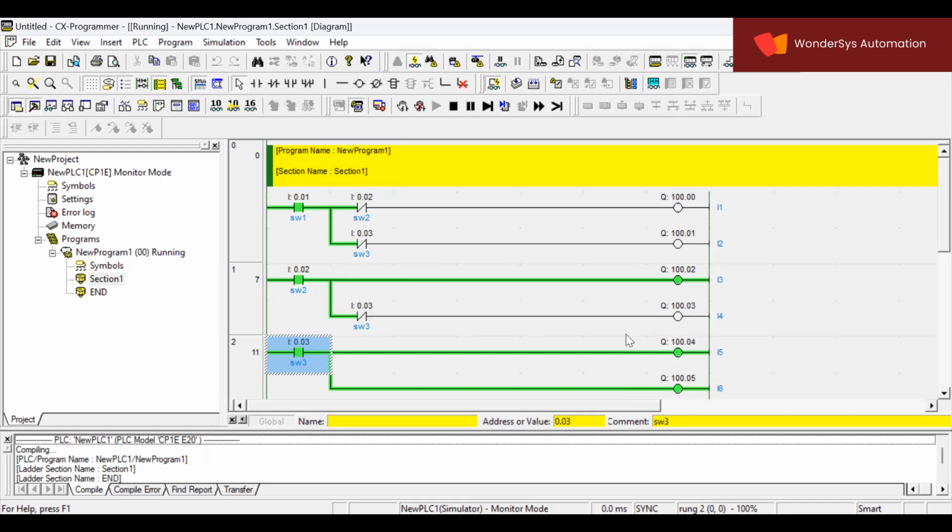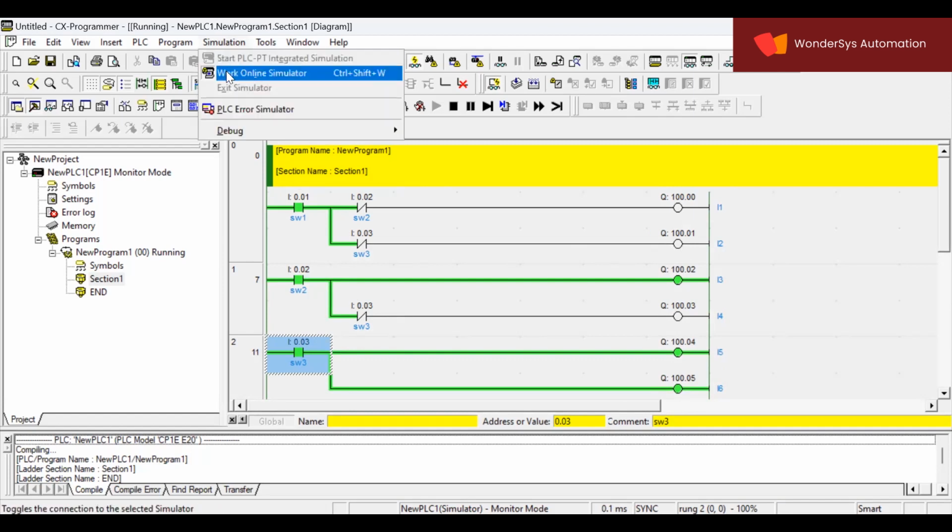So these two problems are of patterns, and they explain the basic rules. You can connect the outputs only in parallel connection. You can repeat the input addresses. So whatever the four rules are, these two will be explaining that. There is one more also, and that is also for understanding the rules of ladder diagram. Got it?